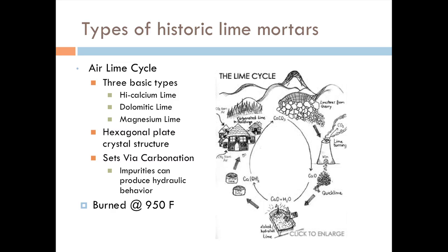The next one is dolomitic limestone. Dolomitic limestone is something that has a little bit of magnesium added to it. It doesn't really work as well, and in fact, you can get dolomitic limestone ready to be used as a masonry mortar from any masonry supply house around the United States. It becomes the primary, not binder, but additive to make modern mortars work. Because without it, it won't work that well. Although there's merit behind high calcium lime being used today, which we're going to get into.